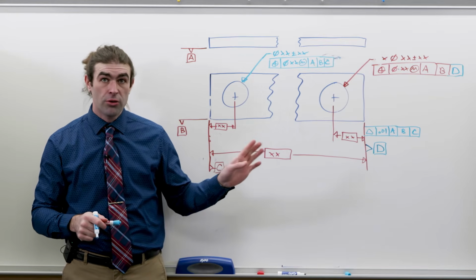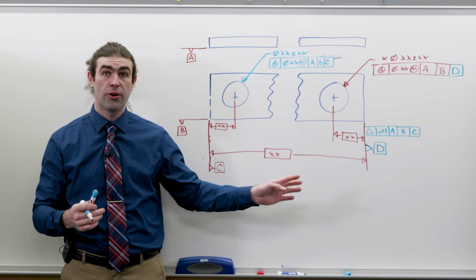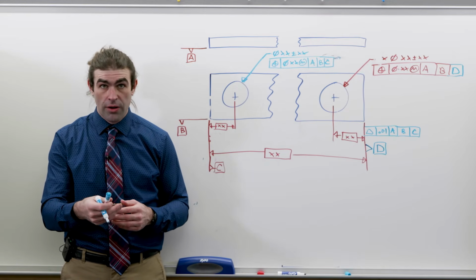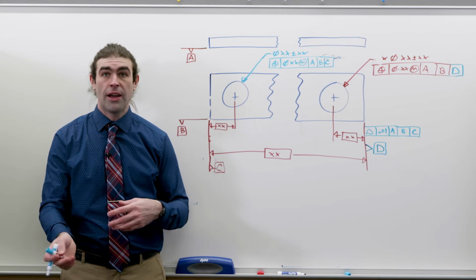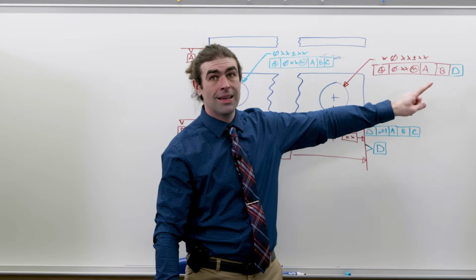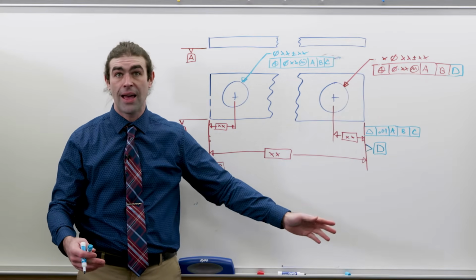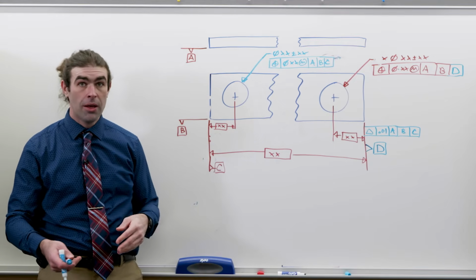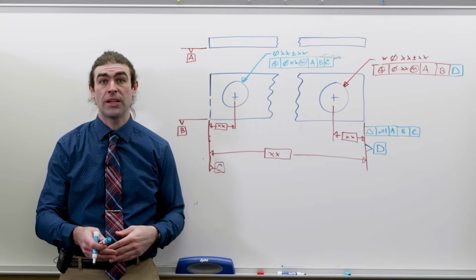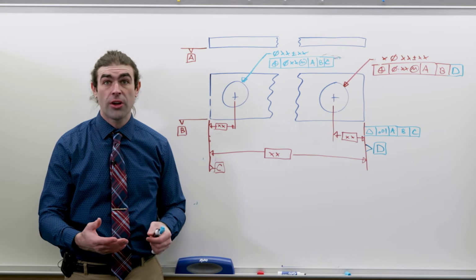Okay? Whenever you do this, though, you're going to introduce extra tolerance stack up whenever you have multiple datum reference frames. It also causes inspectors to have to set up differently, right? So this is a different datum reference frame than this. It requires a different inspection setup to make that happen. If you're programming a CMM, probably a little bit easier, but you still have to remember to punch in the right stuff. So that's it for this first talk about datums.